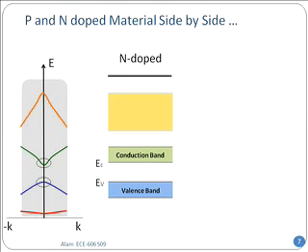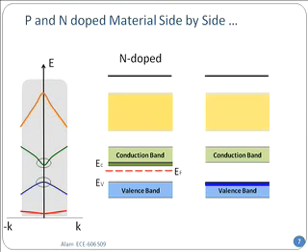Now, if it is an n-type or n-doped material, meaning N_D, then where should the Fermi level be, do you think? Fermi level be close to the conduction band. Is that right? And there will be more electrons and there will be fewer holes. I haven't drawn any holes in the blue band, but you get the idea. Generally, there will be few holes in there, and the deep blue is the number of electrons. So, the initial part is full of electrons. Okay, no problem. Now, what about the other region?